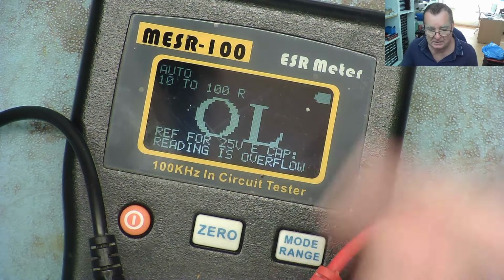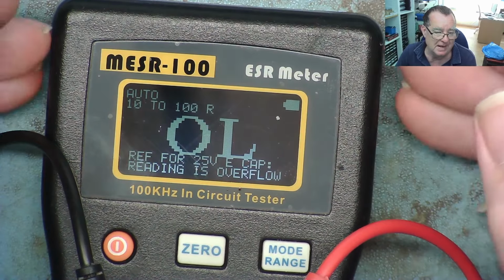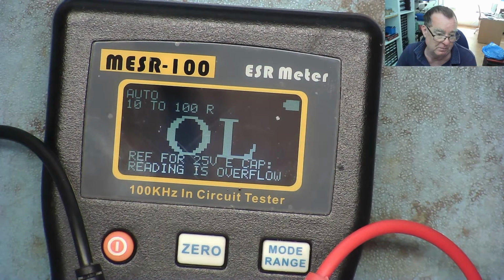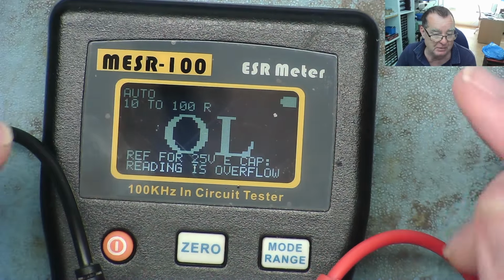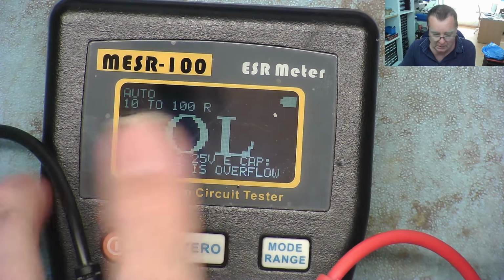So there you go, guys. That's how you test inductors and how you measure inductors with an ESR meter. 0.628. Just remember it, 0.628. Yeah. The resistance equals 0.628 times the inductance, and the inductance is resistance divided by 0.628. Stick the formulas on the back of your meter. Just stick them on there with a sticker. Yeah. That's all you need to do.